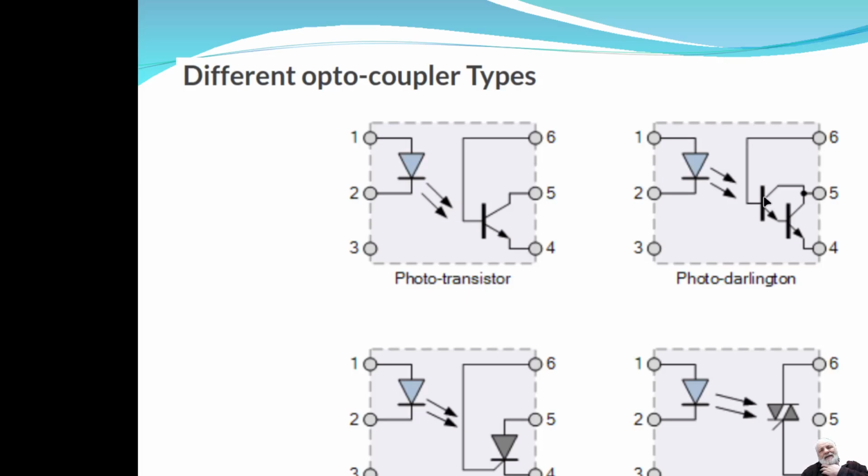You have one transistor that powers a second transistor, and the advantage is that you can get far more current. Let's say you had a gain of 10 on each of these. You would have your current from the first one, and then your current for the second one could be 10 times that. So you get a multiplication factor of 10 times 10, like a 100 times current increase.